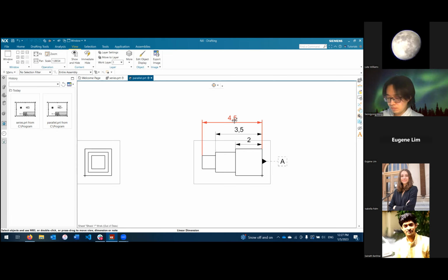And so this concept is a little bit more into when you're getting into really precise tolerancing, and you care a lot more about where they hit on that range. But essentially, that's the difference. It says slightly different things to the machinist when you do limit dimensioning versus plus-minus dimensioning.